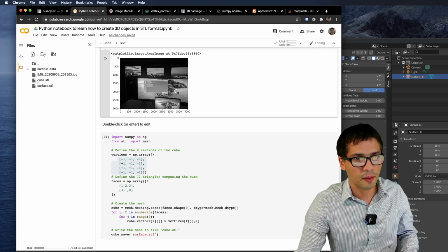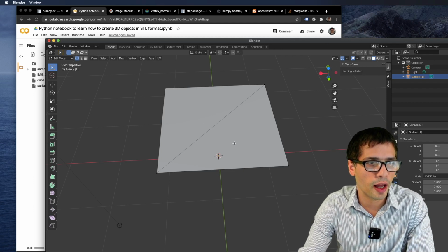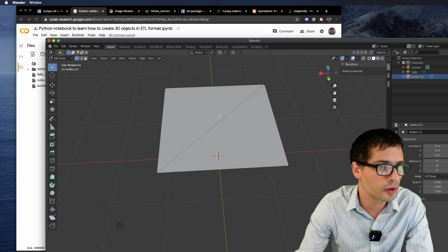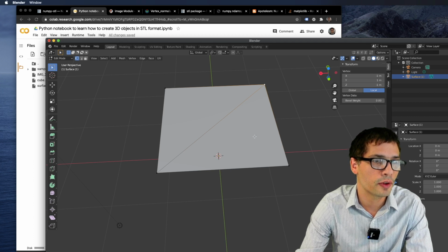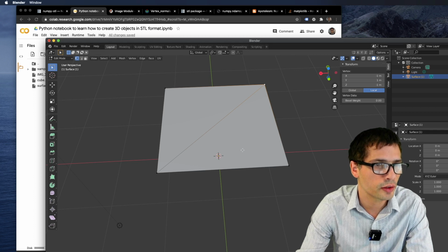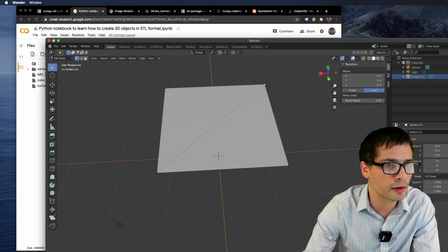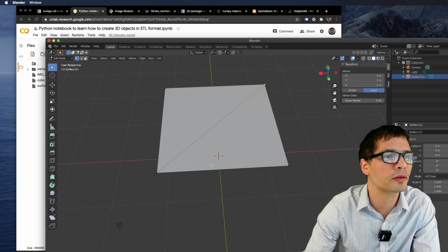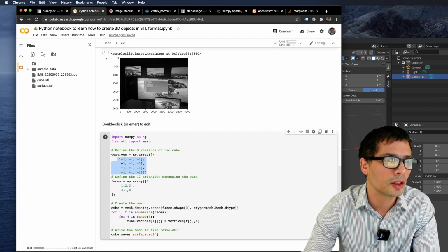Okay, so I want to change the pixel intensity of each coordinate in the lithoplane, right? So I'm not going to be able to do that with this shape here. If you look at it in detail, I could change the height of this vertex, but all the vertices inside here, there's no vertices basically. All the points inside this surface, I couldn't change at all. So it's not feasible. So I need to divide this square into many more triangles than what I have right now.